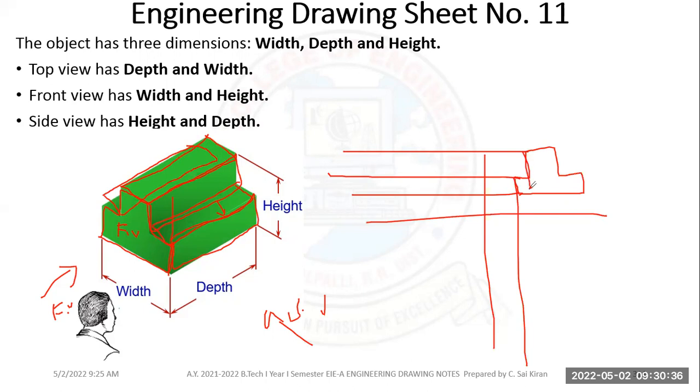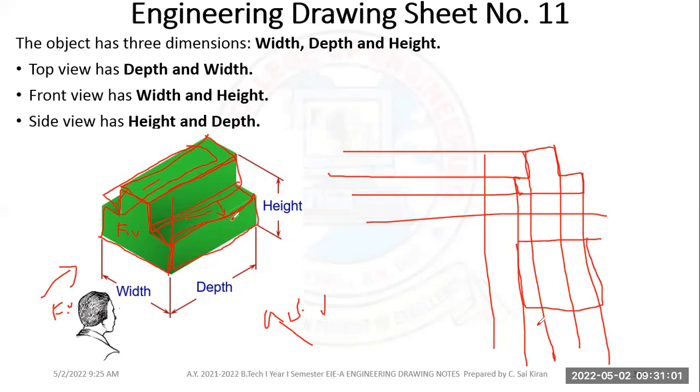Make the projections down, you can see the top view. Okay, and from here give a certain distance, then draw the top view. In the top view, this distance is this one. So these are the distances. Know the depth, give the depth here, close. And you can see this is one rectangle, second rectangle, and third rectangle. You can see the same projections.